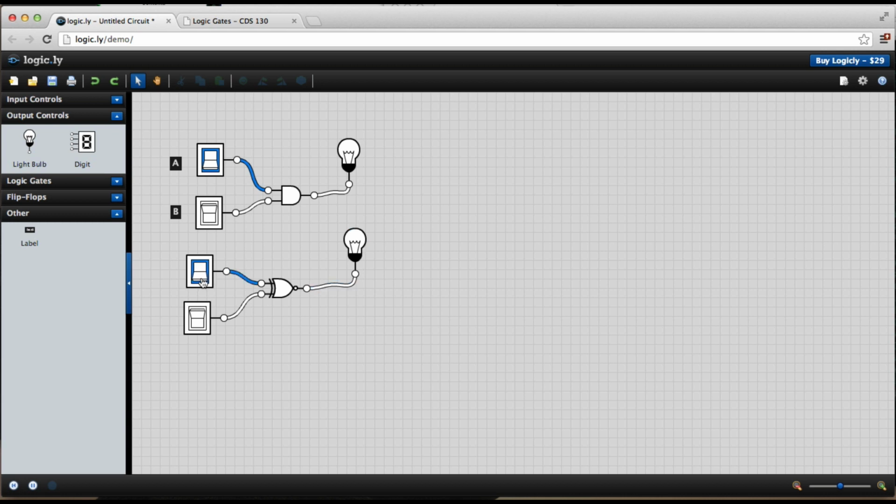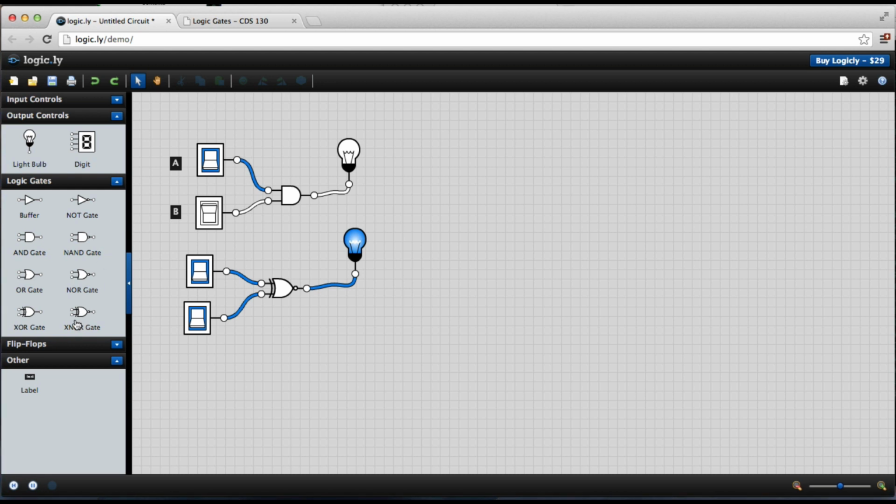This being on, so now if input A is 1 and input B is 0, you get 0 output. Reverse of that, 0 output. Both on, on. So this is an exclusive NOR gate, XNOR gate. And this is the logic table it implements. Both on, output is 1, and both off, output is 1.